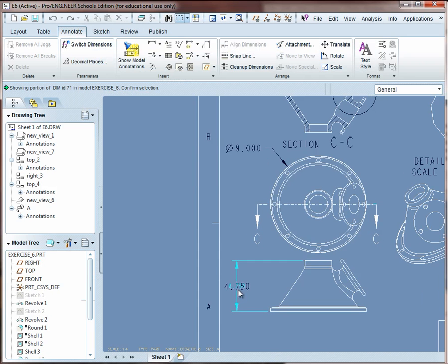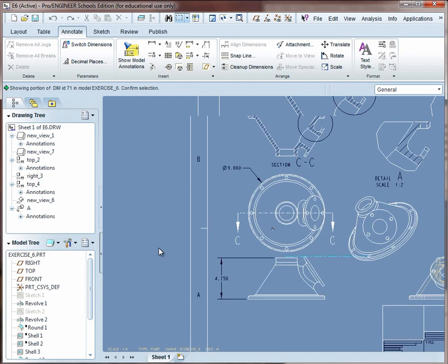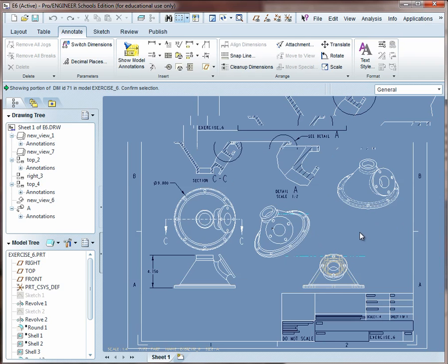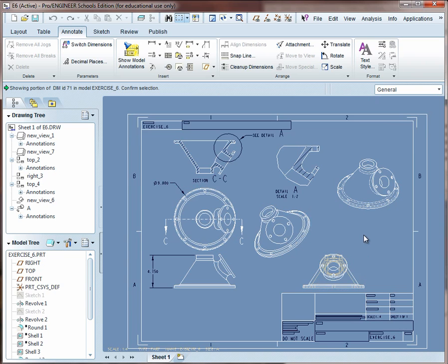And the dimensions now, you can't see it yet until you refresh. You can kind of see a preview there. But hit the refresh or repaint, and now they're smaller. So you could change and adjust things pretty easily there. The only thing that doesn't necessarily change are some of the settings, like for example hidden lines and hidden lines removed on drawing views that are already pre-existing. You might have to change those individually, as you see here.